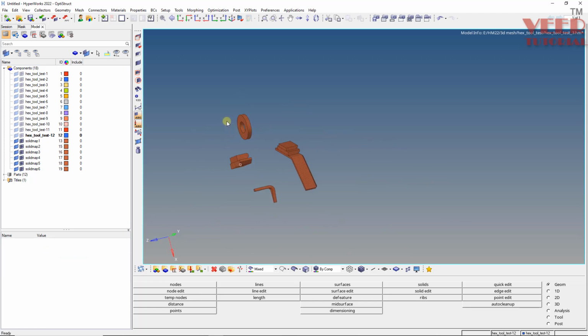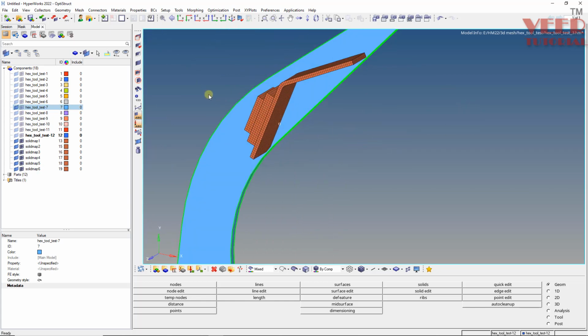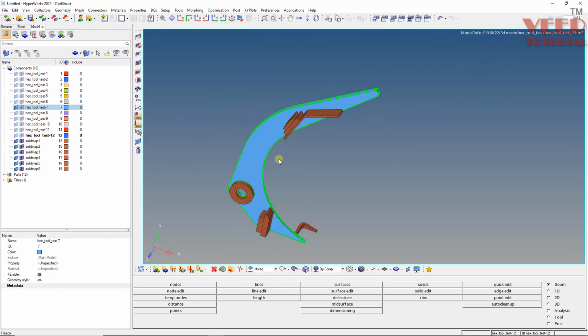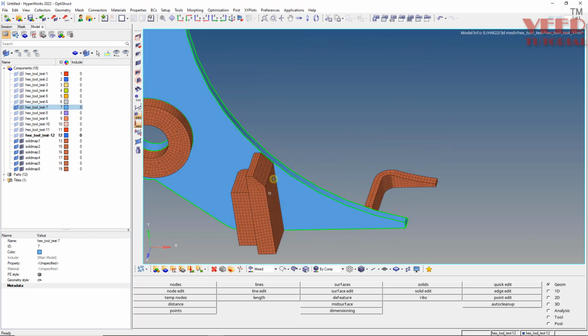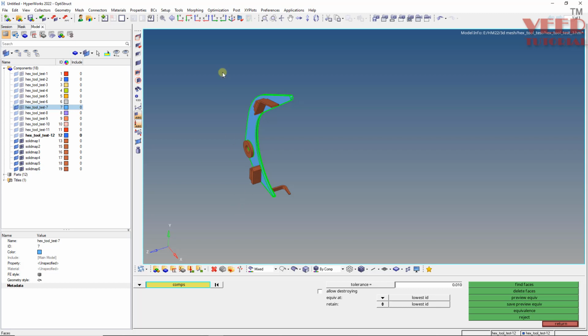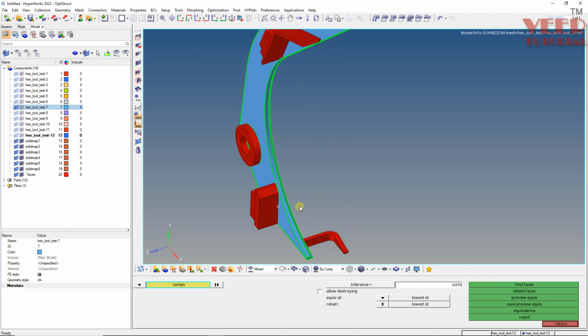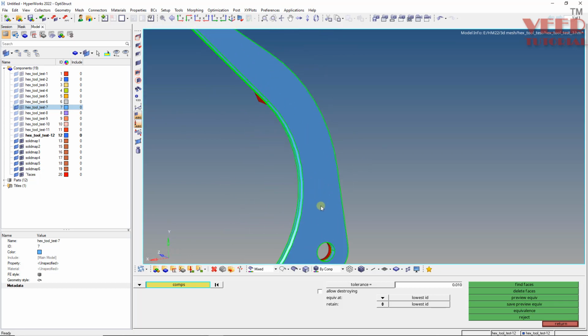Now we also have to turn on this. Is this 7? Okay, this 7. Now you can see this plate is connected with multiple parts. To have a connection, we need to take their faces. So I will take the faces here, go to X, select all components, I will take faces. Whatever we need, I will move it into the collector of this bigger plate.